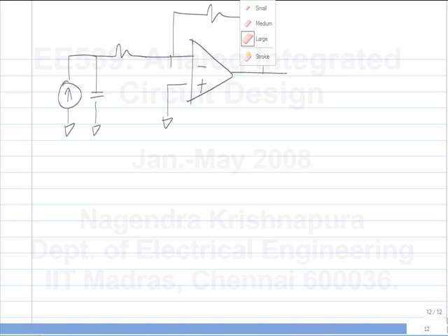Yet another solution that was given was to do this. Okay. Does this work? Doesn't work. What do you think? It works. Why do you say it doesn't work? Or what does it do? No, I mean the pole was already there, right? So what is this doing? It is reducing the loop gain. So it's actually doing both. It is reducing the loop gain and pushing the pole frequency outwards.